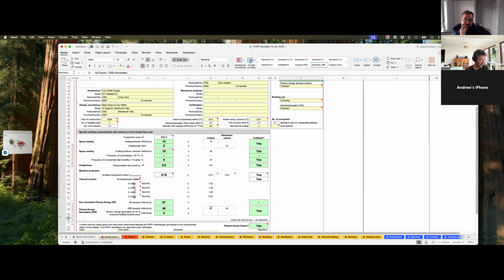Again, on this group, there's a lot of solar installers on there, and they seem to say base it on your winter usage, basically. Bear in mind that winter generation is very efficient because the panels are cooler. Yes, that's right. A lot of people fall into the trap of not thinking that, but it is very efficient in winter. I guess it comes down to the slope the panels are on as well. Yeah, you just don't have the biggest window. Yes, that's right. So, yeah.